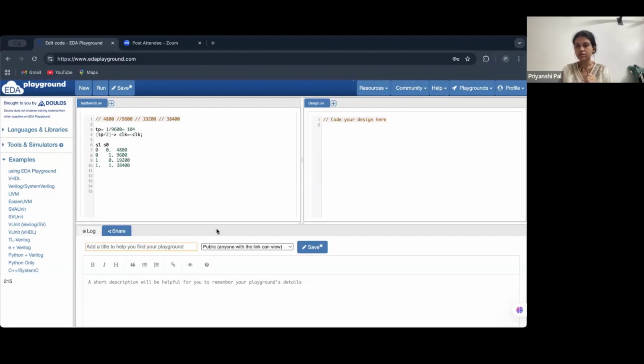Then once our master has the data, it will again send the request to the LCD display, which is the slave. The slave will capture it again. If the address is invalid, it will send NACK.